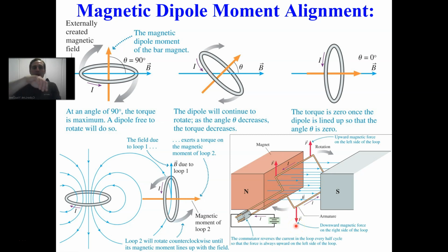Because otherwise you could imagine the torque would cause these loops to turn over and then overshoot, and then it would turn back over and then turn back over, so it would just keep flopping around. Instead, with a motor, we want the rotation to go the same direction, so we cleverly use this commutator and these brushes to change the direction of the current every half turn. And hence, that's essentially very much like an alternating electric current direction that this armature of wires receives.